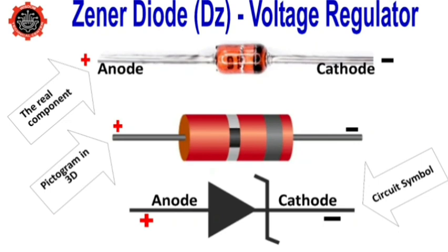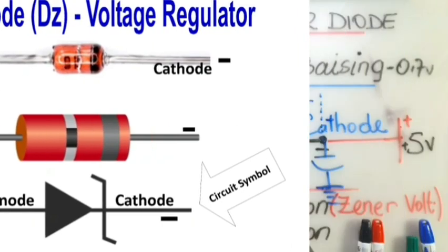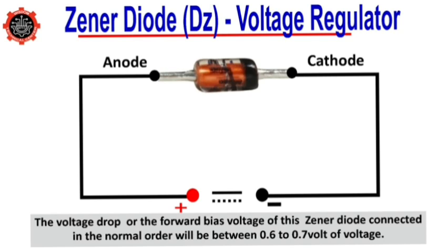That is, na some kind of diode wey dey maintain a constant voltage, and its schematic symbol dey as shown here. The pictogram of this component also get the form like the other previous diodes dem wey we don see. Now, whenever we connect a Zener diode in the right direction as shown on the diagram, the Zener diode go function like a normal silicon diode. That is, the current go flow from the anode to the cathode.